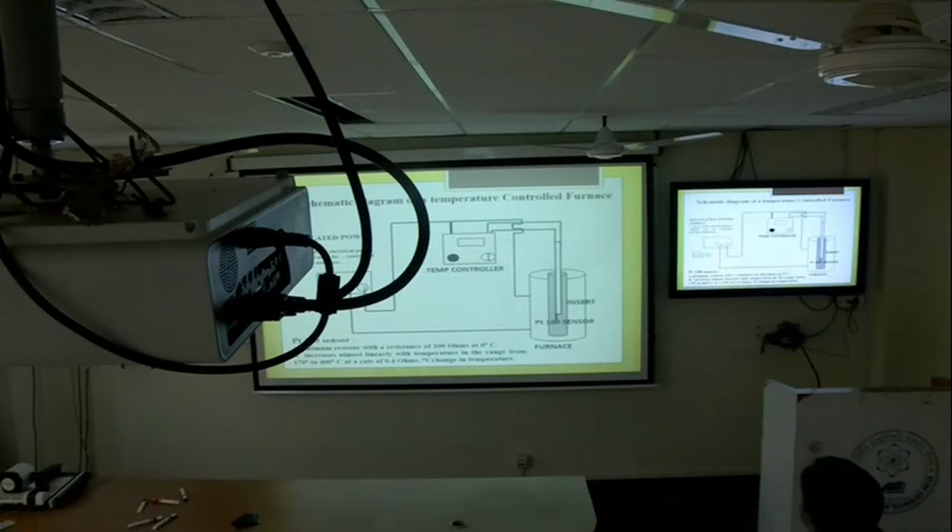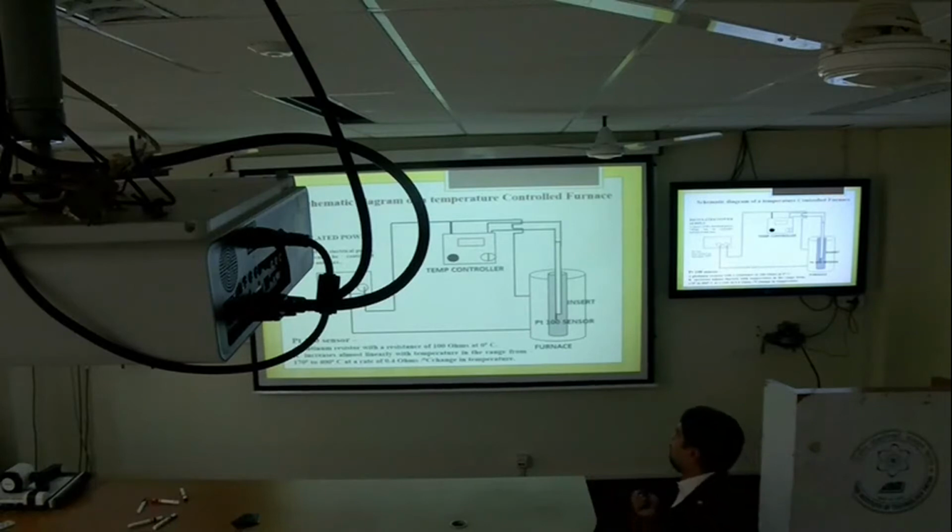Here you have to set it on your own. It will show you only the value of temperature basically. You have to regulate here because the supply is at this end. It is a DC electrical supply which can be varied from 0 to 4 to 5 ampere depending on the load. The voltage you can vary is from 0 to 30 volt DC. The maximum power consumption is 60 watt and the maximum current for this insert is 2 ampere.